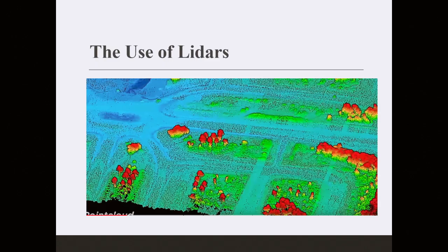You're having wind. So you have three possible deformations. We live in a 3D space. So it could go like this, or like this. Or it could go like this, or like this. You have triaxial, so any inclination around any of the axes would result in an inclined ray, right? It takes that into consideration by measuring the angle of your twist. And it's automatically factored in on capturing the surface or the level where it comes back off.